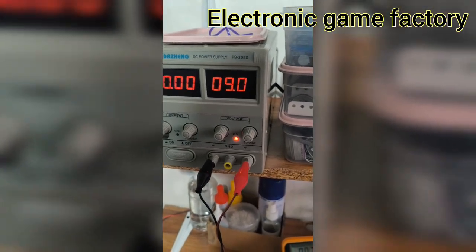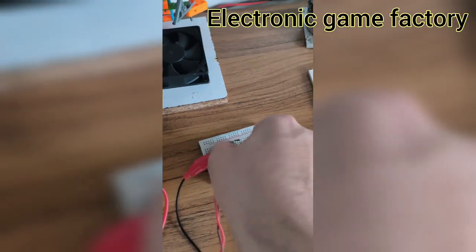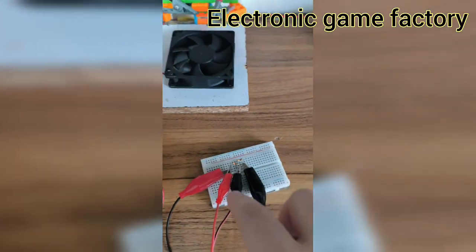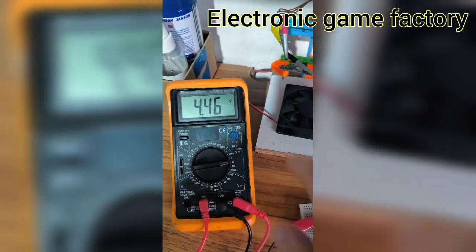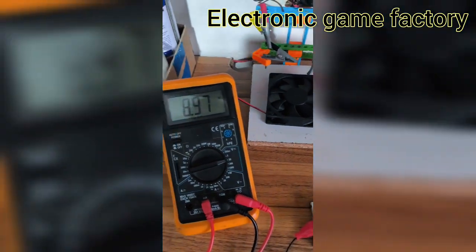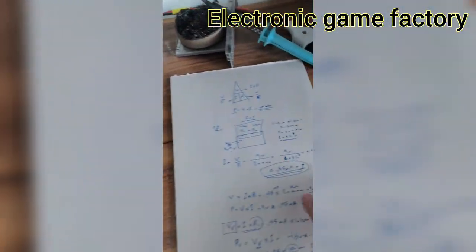As you can see here, we have positive and negative of the voltage power supply, and if I put the negative in the middle, you can see the voltage will be 4.46, and if I put it on the right side, connected to GND, the voltage is 8.97. I mean, it's nearly the 9-volt battery.